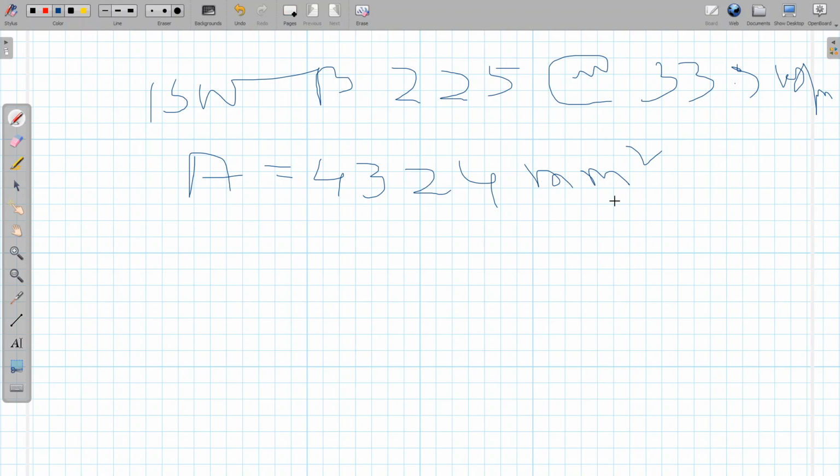Okay, I have just done this to show you whether our section is satisfying. We are satisfying, but there may be other sections in between that also satisfy. So that's why I am taking a section with a lower value of cross-sectional area. What is its r minimum, or r_yy? This value is given in the steel table as 32.2 mm.